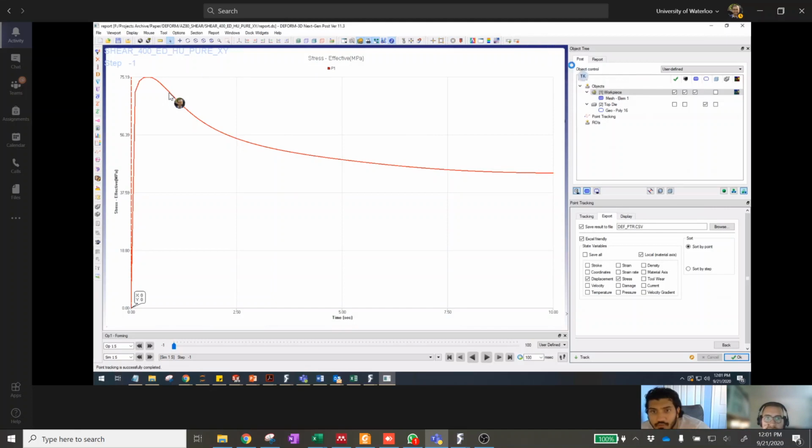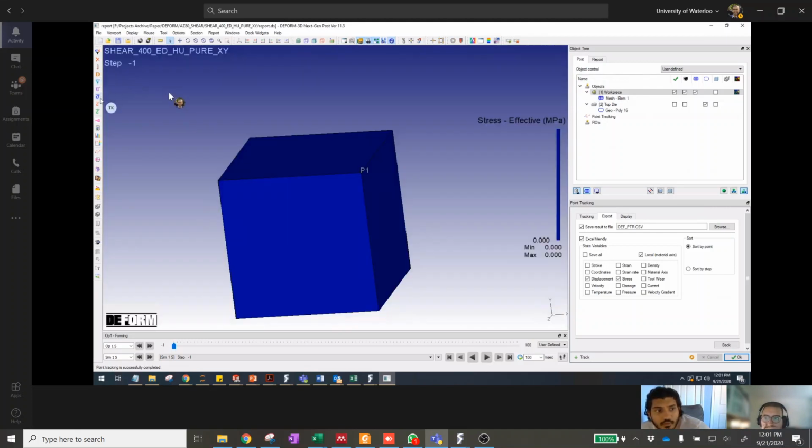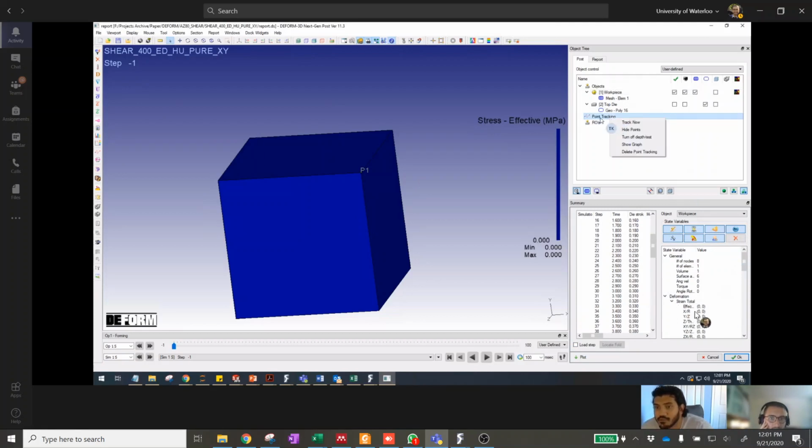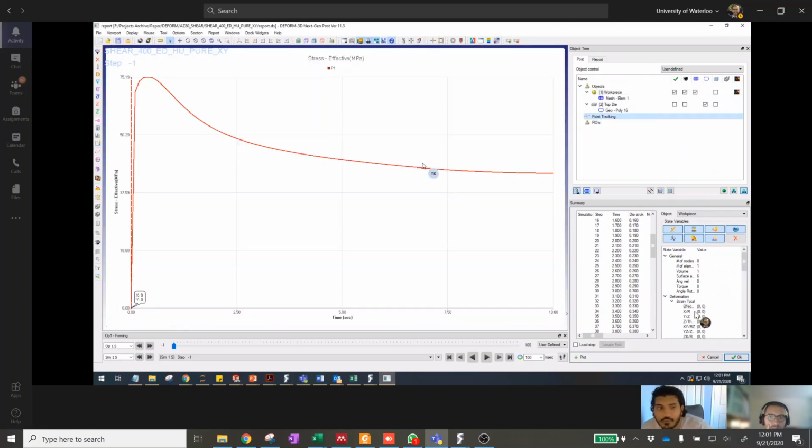No, that's not right. Okay, go back to the plotting feature, the summary. It was in summary. Load step. No. There was a drop-down menu that had stress and the effectives were non-zero. So that was here. I went show graph. Here we go. That gives you strain.